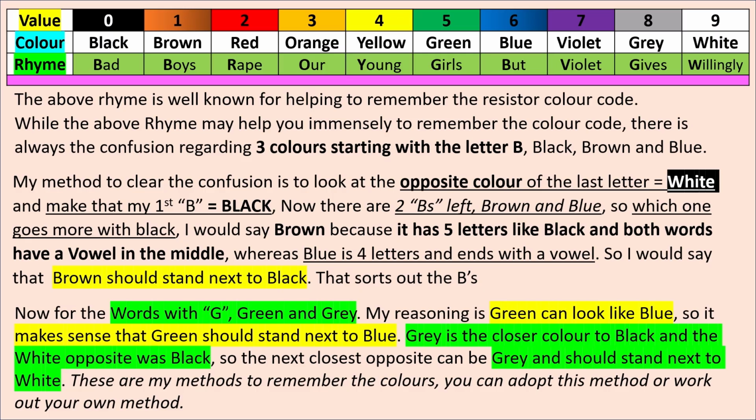Now, the next value is the one which gives us how many zeros we need to attach after the 3, 4. So if we have a color like brown, we would only have 1 zero. If we have the color black, we'd have no zeros. So the value of that resistor would just be 34 ohms.